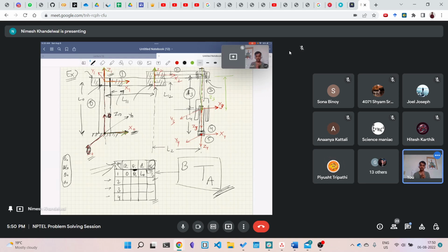That will change. But see, theta and d are actually what gives your robot the motion that it has. So in most cases, changing the frame should not change these parameters. If it is changing these parameters, then maybe you are not assigning the frame at a proper place, and it might make things hard as you go forward.